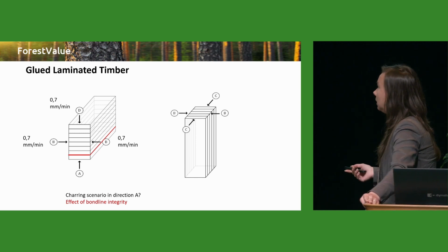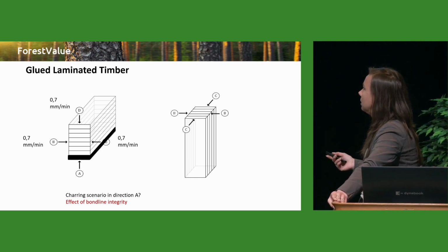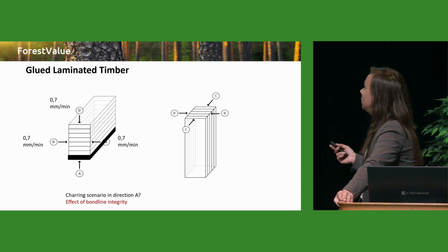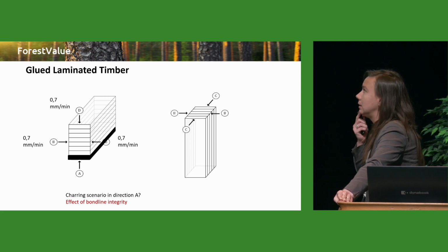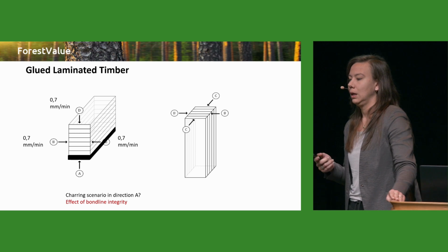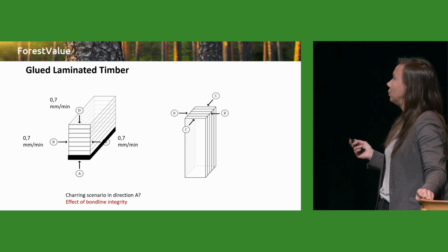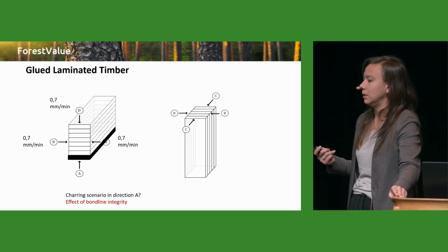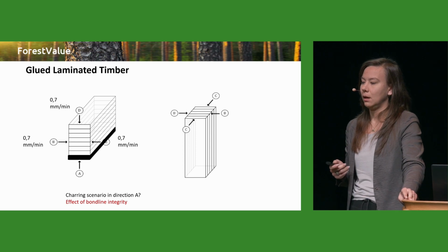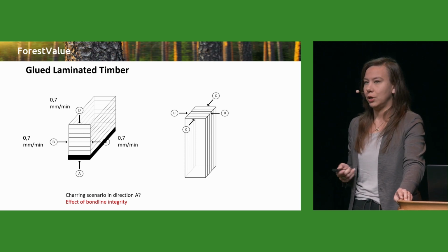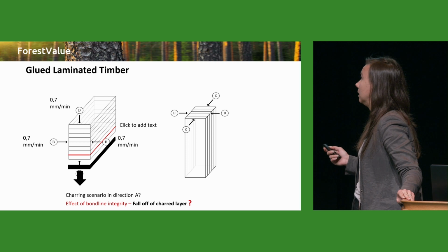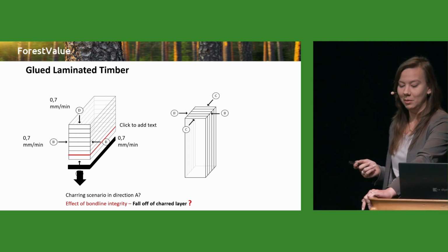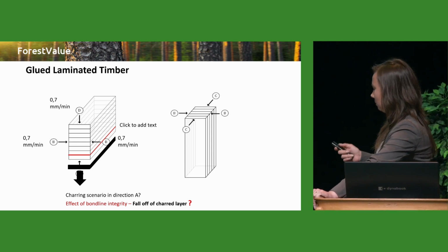However, with our test series, we had observed also some adhesive systems, some bonding systems which do exhibit the fall off of charred layer also for glue laminated timber.